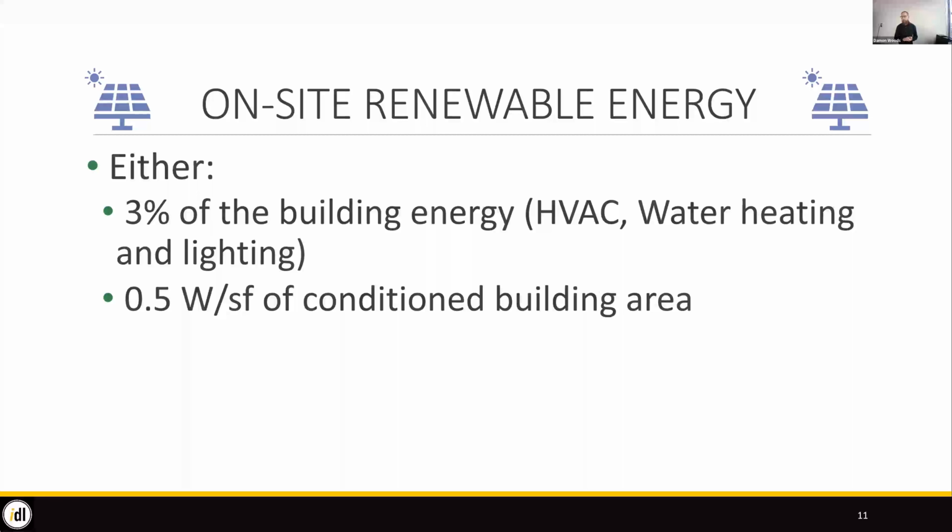In Boise, we also have access to geothermal, which not many places do. So if you do hook up your building to geothermal, as long as it provides 1.7 BTU per hour per square foot, which you easily get out of the geothermal, then you would meet this on-site renewable energy credit. Something specific to Boise that might be helpful. And I know City of Boise is trying to expand their geothermal network, although it's not always easy due to the backup systems that are occasionally needed.